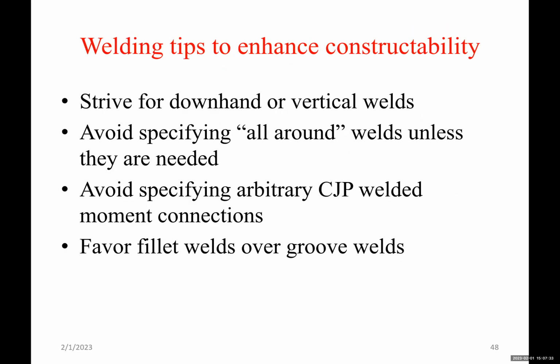Okay, welding tips to enhance constructability. Strive for downhand or vertical welds. So when you design the welds and show the welds, try to do it downhand and vertical. Avoid specifying all around welds unless they are needed. Okay, many engineers do that, all around welds.